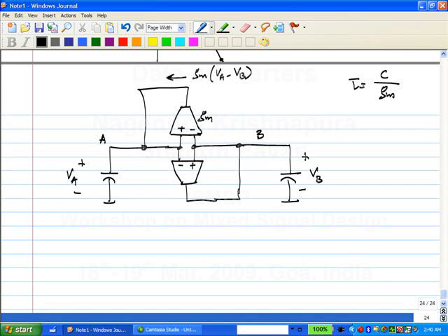Okay. So a couple of practical issues. One, of course, is that please note that we don't want to figure out if VA is greater than VB. Okay. Whatever. Get them to VDD or minus VDD and then go to sleep. You understand? What should we do? After you made the decision, if we all go to sleep, what will happen? What else? The next input has to be digitized also, isn't it? So what should happen? You must have some way of, this is not just good enough. We should have some way of being able to store the inputs onto VA and VB after you do this.